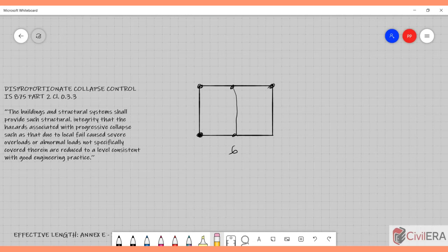In the same way, if you have a structure like this, and provided you have an excellent design here, say in case this beam fails, again the slab should not collapse, it should have some bridgeability. At least for the unfactored load, this should be able to span as a two-way slab like this. So you may have to tweak your detail, slightly adjust your curtailment, lapping location and all that, and ensure that you have bridgeability.